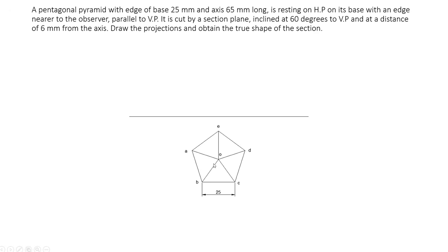Draw the slant lines, that is, locate the apex or centroid. To locate the centroid of a pentagon, draw a line from one corner to the opposite edge's midpoint, and another from another corner to the opposite edge's midpoint. Those two lines will meet here. So that is the apex. Erase the part of the lines that goes to the edge midpoints. You only need to draw 5 lines from the 5 corners. Connect the apex to all 5 corners, erase all the unwanted lines, and name that point O.